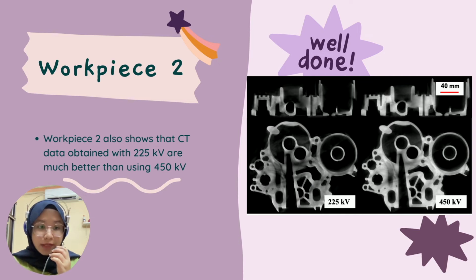So, when comparing the CT results of workpiece number 1 and workpiece number 2, it can be clearly seen that measurements with the microfocus tube are generally more suitable for non-destructive testing, defect characterization and detection, and that they are particularly useful when dealing with fine structures and small flaws. However, CT measurements with the high energy 450 kV tube are typically more suited for dimension measurements and for obtaining the geometry of the investigated workpiece, since there are fewer artifacts and the surface of the workpiece may be segmented more precisely than with a low energy tube.